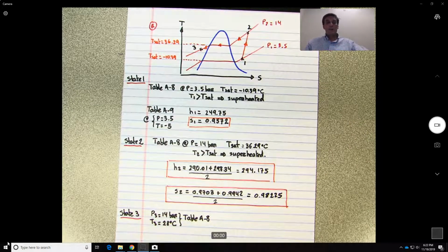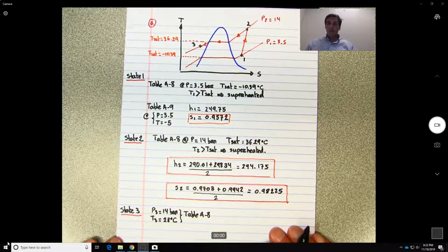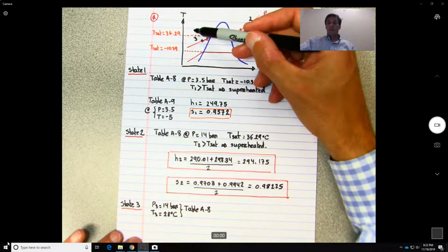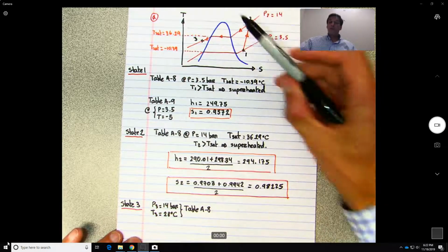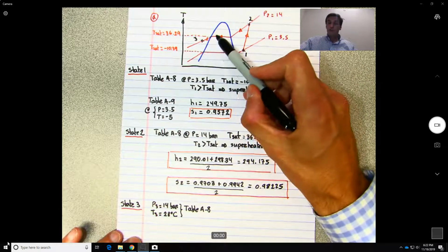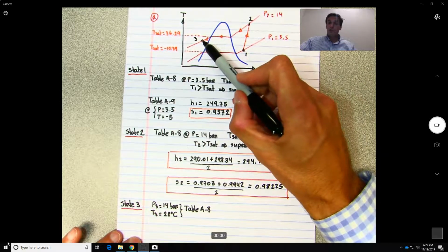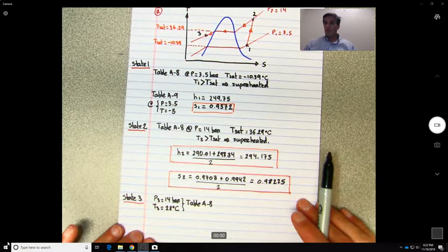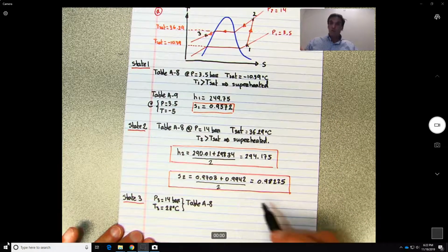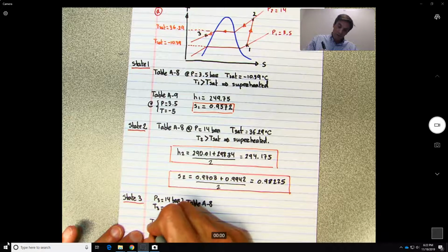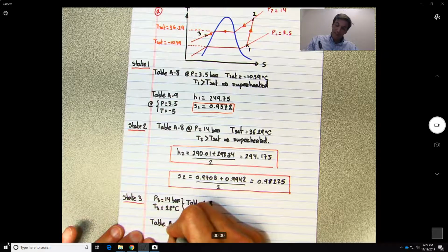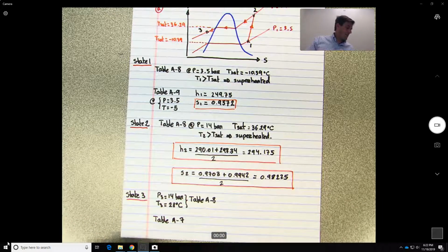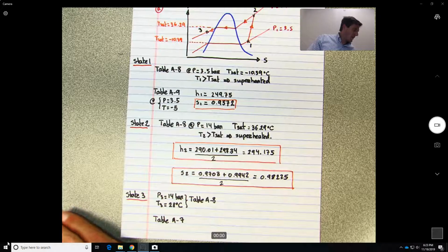That one is a little bit more complicated, because if you remember, we don't have tables for saturated liquids in this area, but we say that the properties do not change much as a function of the pressure. So in order to find the value of the property, we only need to consider the temperature. That means we need to go to table A7. So what is table A7?